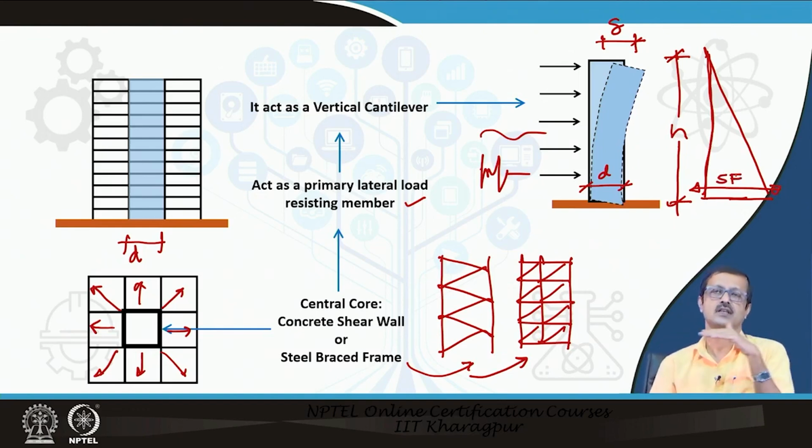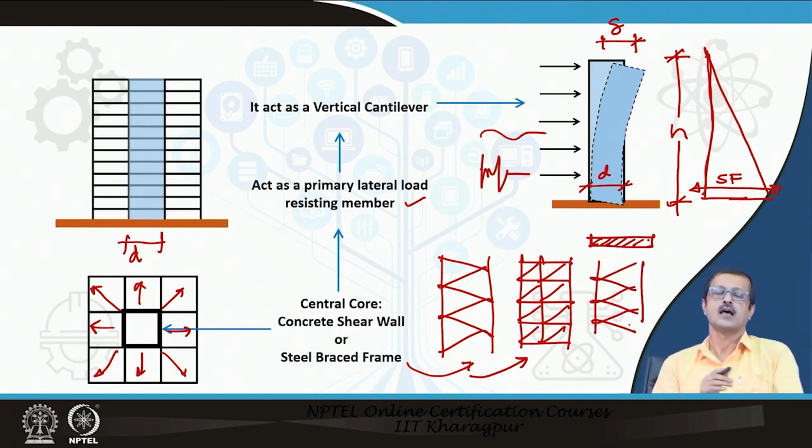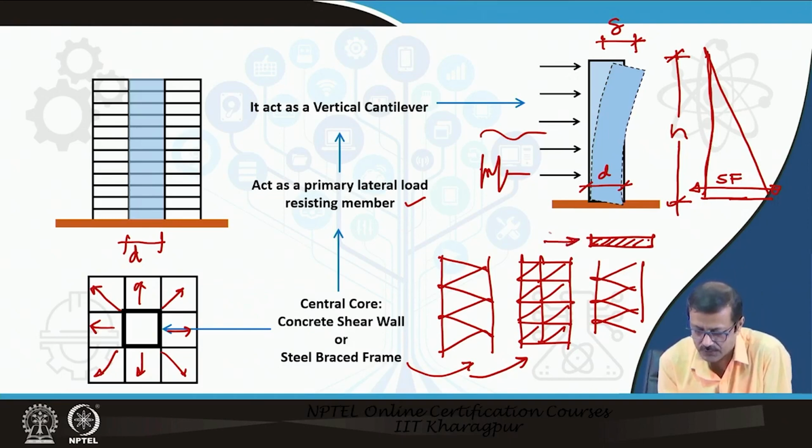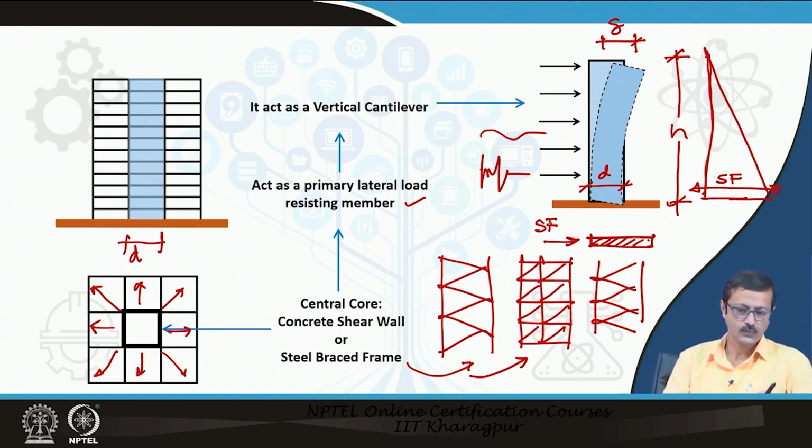And this shear has to be taken into account. So that is why you need, at the base, the shear wall or this particular bracing, which I have just now shown, where you have to intensify the quantum of structural material so that it can resist the shear force. The shear force has to be resisted. That is actually happening in the ground plane.